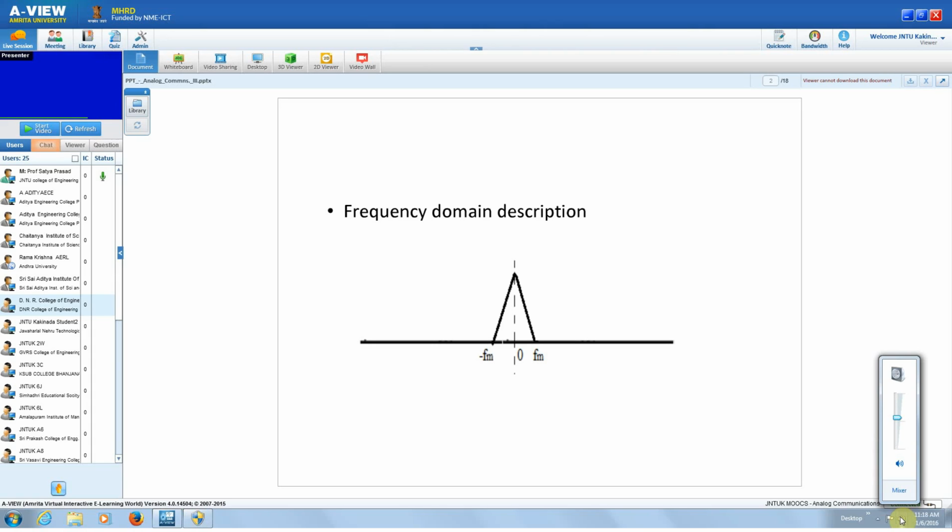One thing is your m of t should have less amplitude compared to your carrier, and this carrier is generated at the receiver, so you can have the required amplitude or power. Therefore, you can get the original signal of coherent detection. Similarly, you can derive for your SSB signal also; you get the same variation as that of coherent detection of your SSB-SC signal.